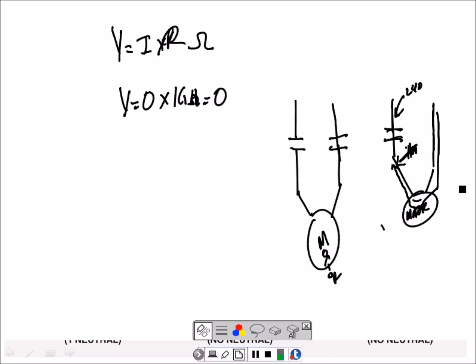Yeah, I think I showed y'all. This is actually a residential relay. Now the coil is 24 volts. Y'all understand now that the coil and the relay contacts don't have to be the same voltage, right? So this is actually the relay, or the contactor, that runs a compressor motor on an air conditioning system. And what you'll notice is that one side comes straight through. And I'll pass this around so you can look at it again.